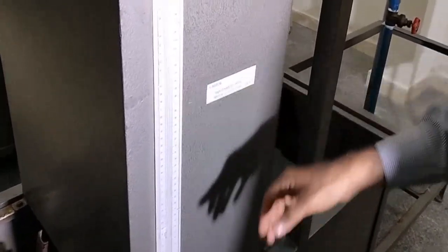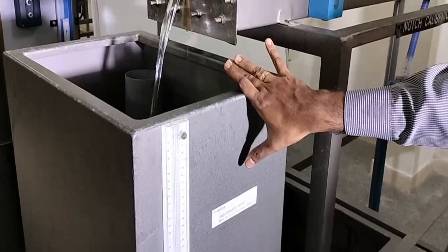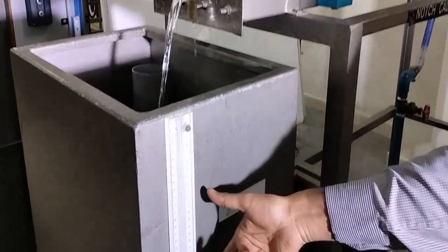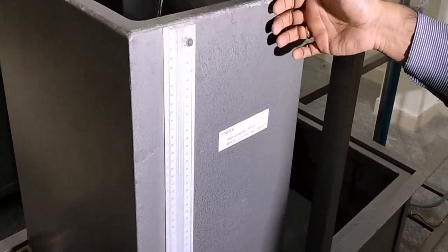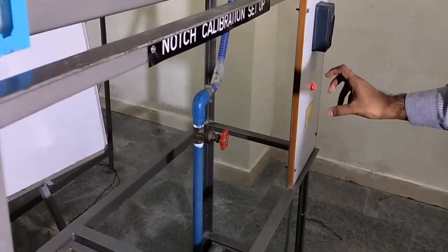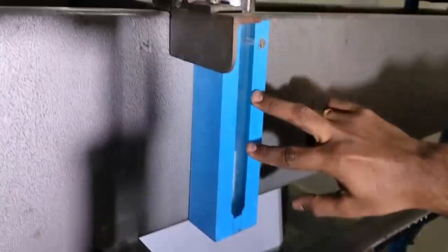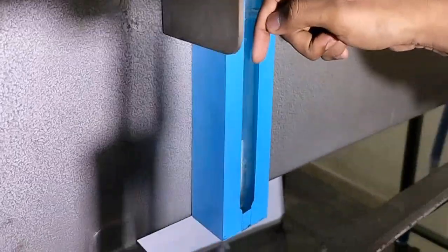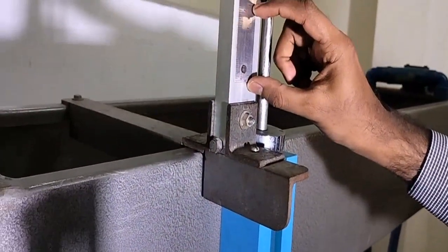I already mentioned this is going to be called the collecting tank, and also you are going to call it the measuring tank, because the measuring scale is attached to this tank. Now, once again the experiment is repeated for the higher discharge. Just change the discharge according to the rise of water using the needle. That needle should be touched to that water level. Then the rise should be noted for the calculation.